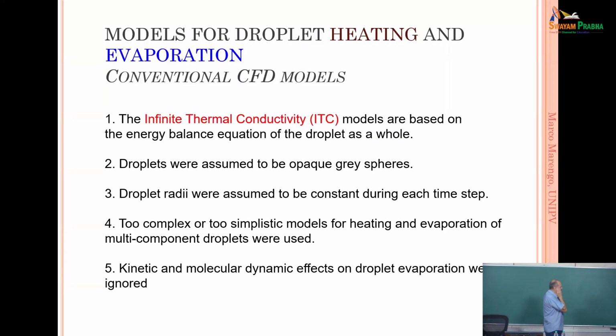This model is very basic, because it considers that the thermal conductivity K of the liquid is infinite. Okay, but the energy balance equation is different, no, this one is different. Sorry, but it is using many CFD simulations. The droplet is assumed to be an opaque gray sphere, and the droplet radius is assumed to be constant during each time step, and kinetic molecular dynamics effects are completely ignored.